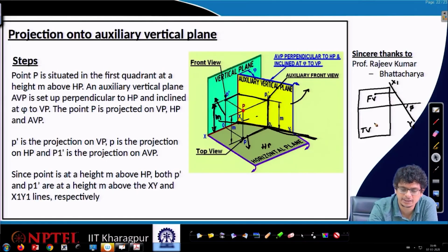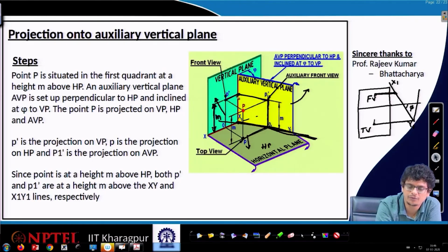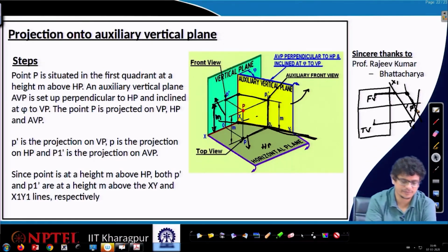So, if we are projecting some point, we rotate it in that direction, it comes all the way there, and this P point projected to there comes to that point on the auxiliary plane, and from there it goes parallel to that line. So, parallel to that line, if we are in a position to construct around that, we will be in a position to construct the views.